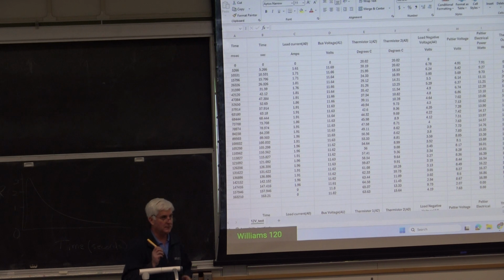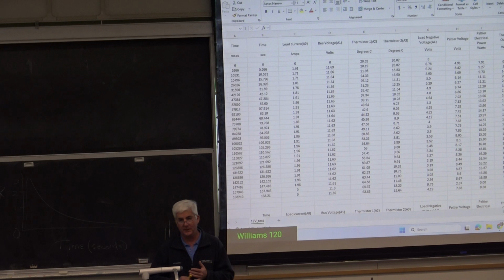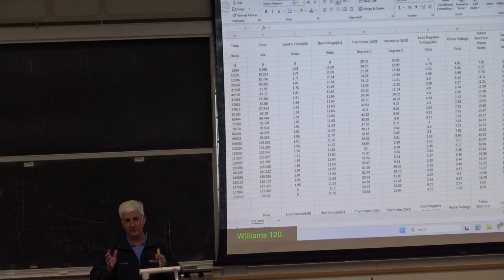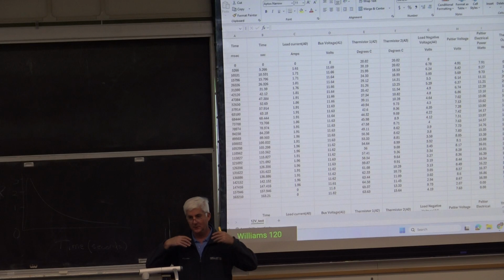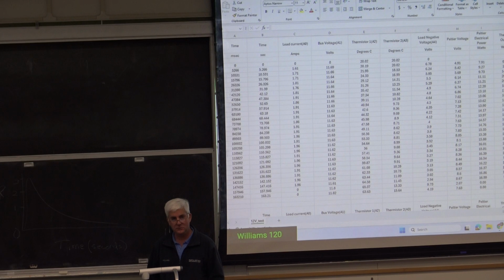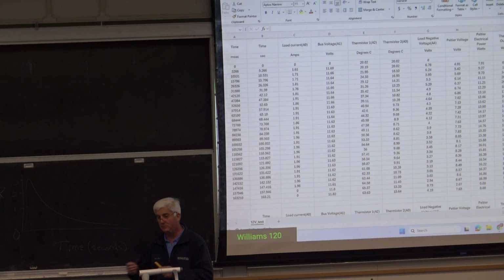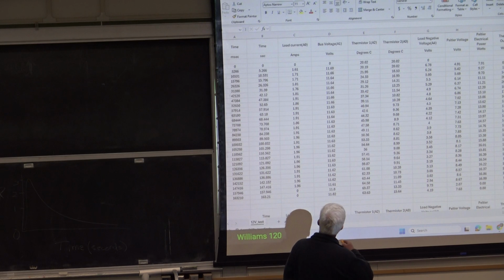Okay, but the subtracting off the MOSFET and the shunt resistor, that got a lot of people. A lot of people also wanted to substitute in numbers for some reason, rather than just solve it symbolically and say, okay, now we put our data in, chug it out, here's the answer. And when people put the numbers in, I went, what data point is this for? One data point doesn't even make any sense, because you have to go between two time periods to get the thermal power.